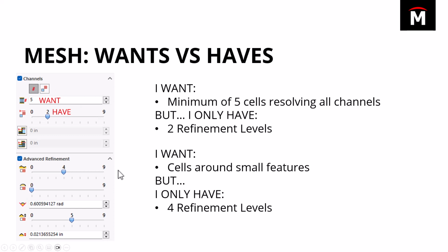But refinement level 4 means if I see a sharp corner, I want refined mesh around that sharp corner because that's where flow is going to kind of circle around and kind of hug that corner. So it'll refine it up to 4 times. The last one that's enabled is down here. This tolerance level is 5.